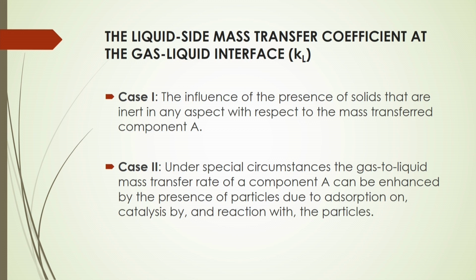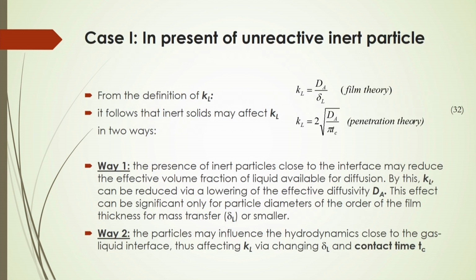Consider the influence of the presence of solids that are inert with respect to the mass transferred component A. In other cases, under special circumstances, the gas to liquid mass transfer rate of component A can be enhanced by the presence of particles because of adsorption on catalyst surfaces or reaction with the particles at their surface.